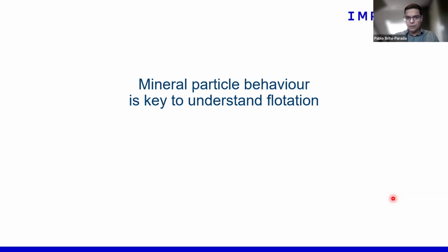You need to use a laser to then be able to track seeding particles that are used. And while you can study flotation devices using PIV, it tends to be very low concentrations of solids, if at all, other than the particles used for the seeding. And that sometimes makes it a bit more complicated. Two-phase systems don't really behave as three-phase mineralized systems, so that poses a challenge.